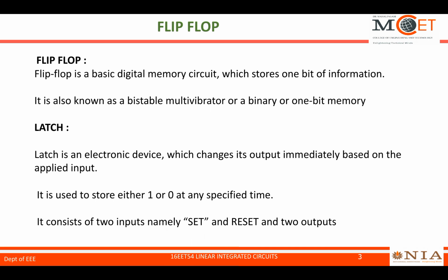So what are the different memory elements used in a synchronous sequential circuit? Flip-flop and latch are the two memory elements. Flip-flop is a basic building block of a synchronous sequential circuit. It is also known as bistable multivibrator, and it is a type of circuit that can store and recall a single bit of information. Its name comes from its ability to flip or flop between the two stable states.